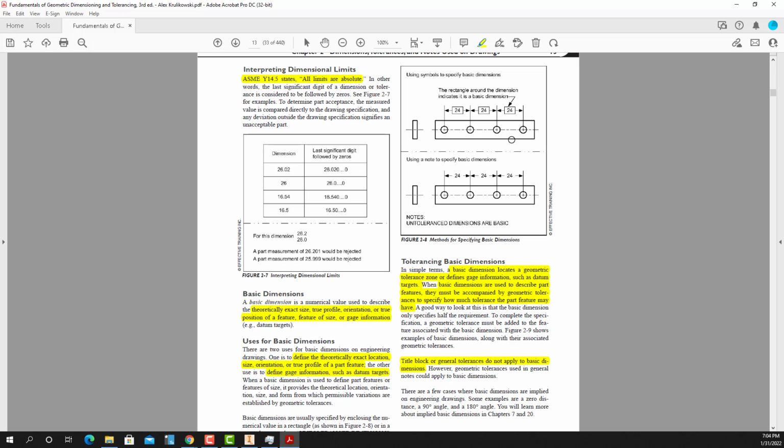That is gauge makers' tolerances. Tool makers, you know, the gauges that measure it, they're extremely accurate. So that's why we can have continuous dimensions like that. We don't have tolerances adding and adding and adding to make a huge tolerance at the end.